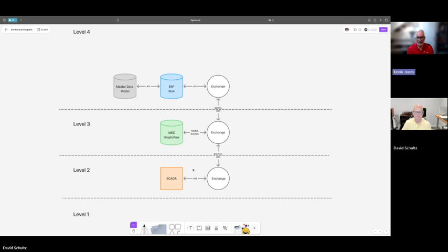And again, that data model is coming from the master data model. It all starts there, and that's why you say start there. Awesome. Yeah, absolutely. And now this is where we're going to start talking about this API, because if your SCADA system has the ability to interrogate the master data model, and parse that information coming through and dynamically build, we'll just call it, the tag structure, that is going to enforce that anytime there's a change up here, that's going to be reflected within our system as well.